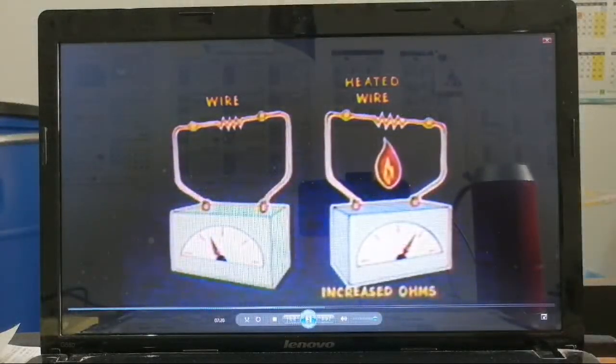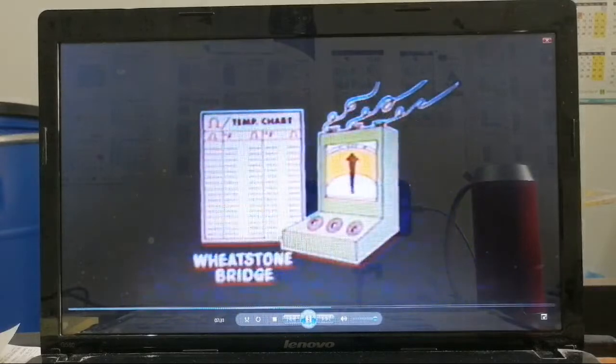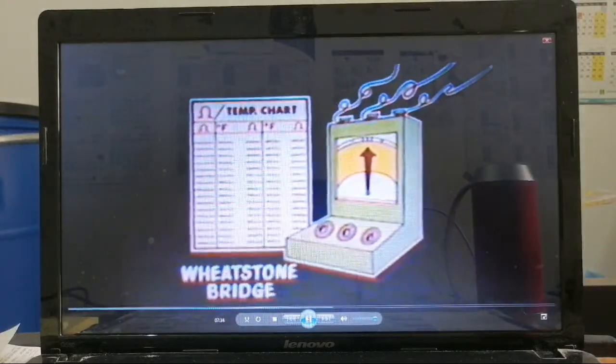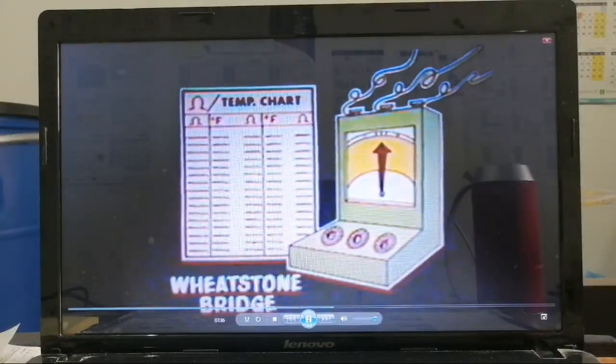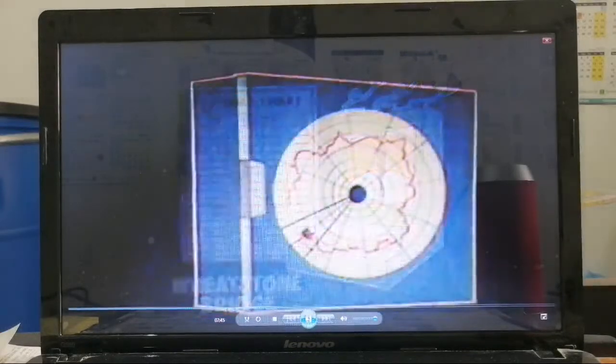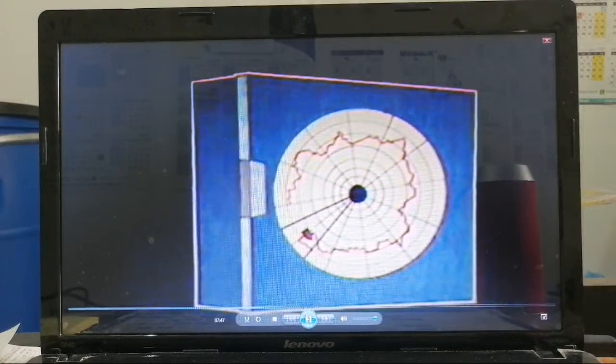Since the electrical resistance, measured in ohms, of most metals increases with temperature, a resistance thermometer can be designed. Instead of just an ohmmeter, this type of instrument uses a Wheatstone bridge to read changes with great accuracy. Here, known and calibrated resistance is used to balance exactly the heated resistance to be measured. This then is referred to a temperature chart or automatic balancing devices which give readings of remote temperature without consulting conversion charts. Often a recorder.